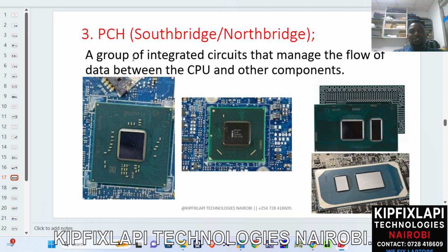The south bridge is a section within this PCH which is responsible for controlling all the input and output devices, that is, the speakers, the keyboards, the ports, the Wi-Fi cards, the DVD players, and the HDDs. While the north bridge is a chipset within the PCH which is responsible for ensuring that the CPU is communicating with high-speed components like the RAM and SSD.